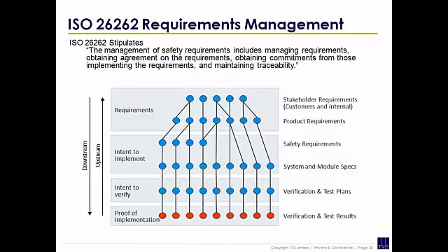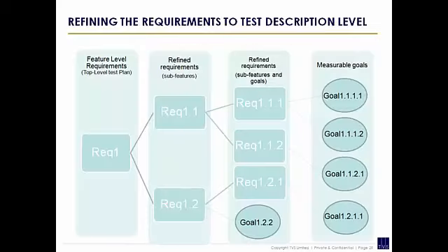Okay, and that's what we do, in our ISO 26262 work and our DO254 work: we break down the requirements. Hopefully you can see here, this is typical. You're breaking requirements down to smaller requirements or features maybe, and you're breaking those down maybe within your requirements analysis tools. So DOORS, most people DOORS users? DOORS, yeah. So DOORS is a big one. Avionics. So maybe you've got this hierarchy within DOORS, okay, and so you've done your requirements tree within DOORS. Then what we would do is map that onto our verification goals.